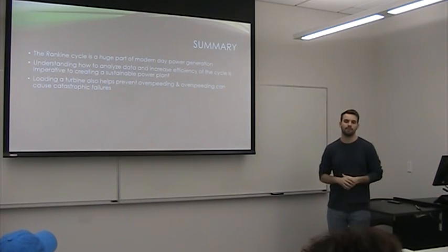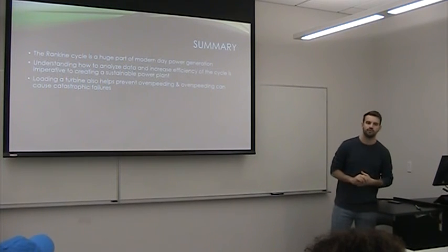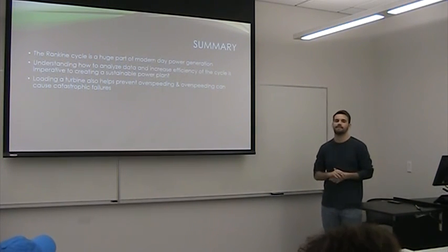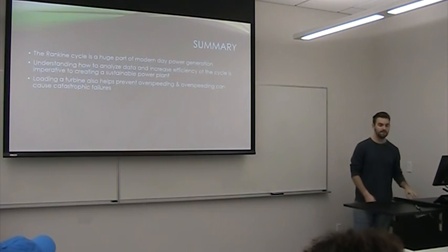Also, loading a turbine will prevent it from overspeeding in most cases. They also usually have trip mechanisms that will trip if it starts to get too fast, and they'll start to cut off everything. An overspeeding turbine is incredibly scary, by the way.